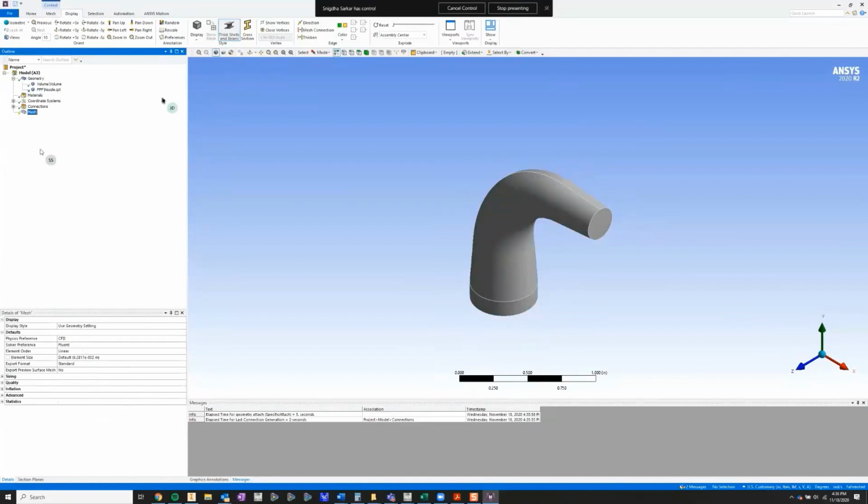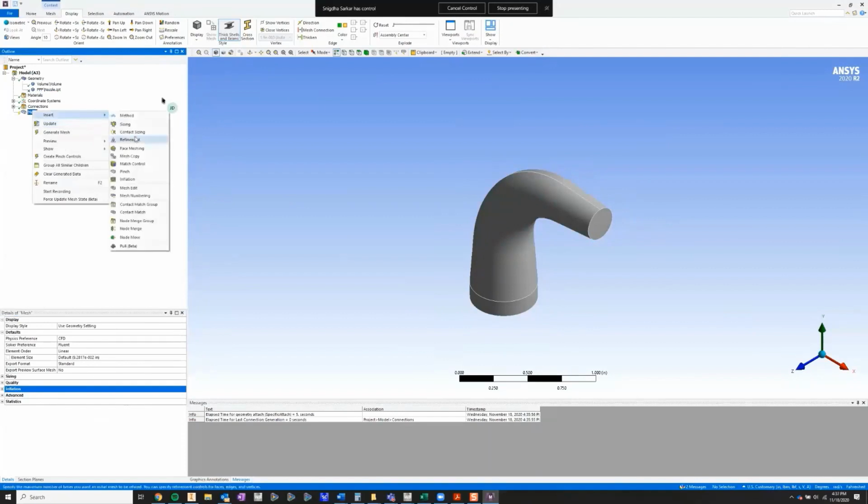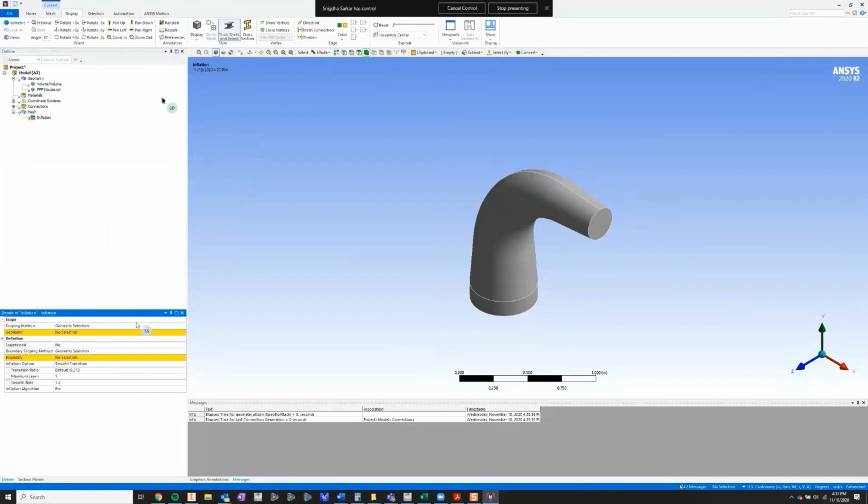Now, for the purpose of this demonstration, we didn't pay a lot of attention to the mesh accuracy and how refined it should be. But if you're setting up an actual case where you're really interested in the values, or you're doing research, make sure that the CFD mesh is good enough and captures all the finer details of the geometry.